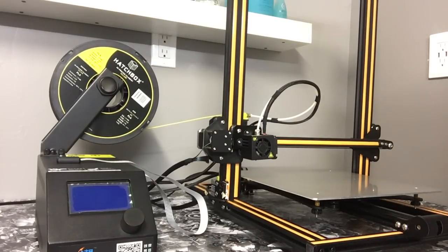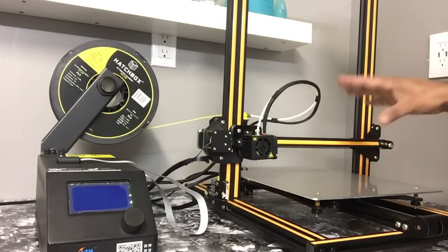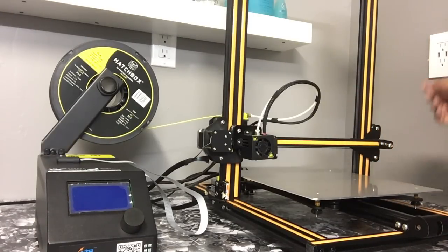Another question somebody had for me was, why is my z-axis, when it's printing, skipping a little bit, or it feels like my belt is loose, or how does that work? Basically, 3D printers, most of the ones I know, work off belts. There's one here, there's one here. When I got this printer here, it was very loose. So what you have to do is go in and make sure you tighten it, get the tension right,